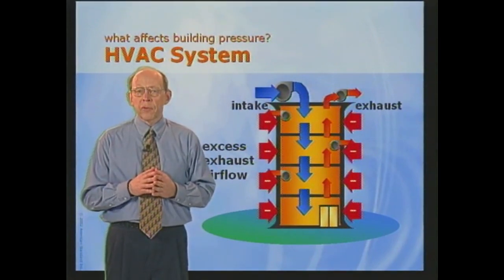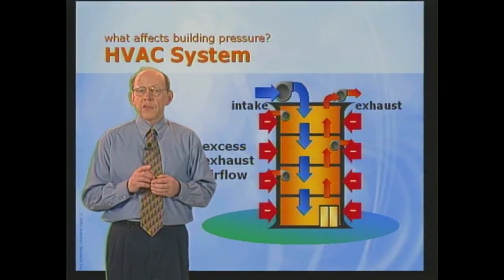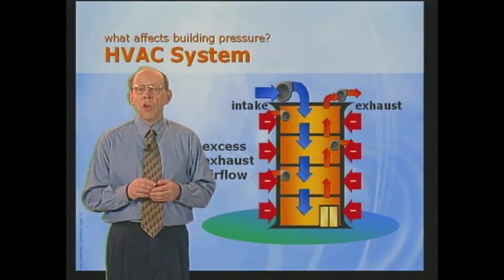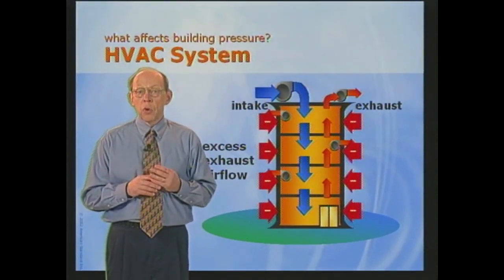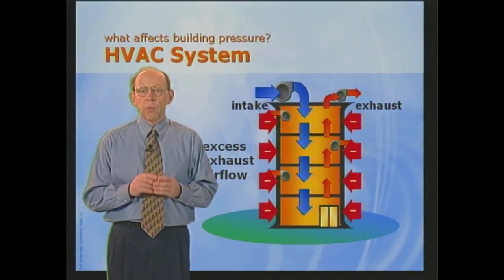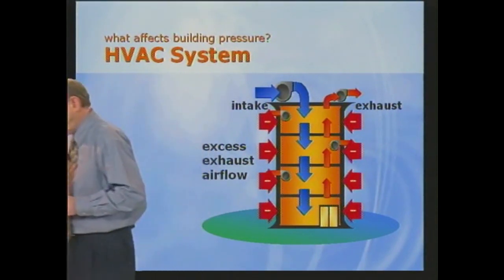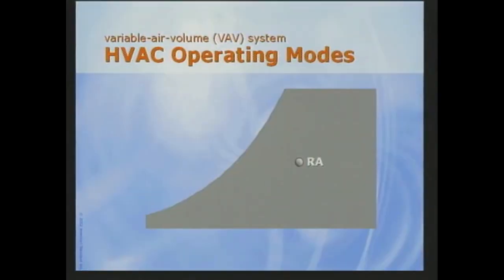Intake and exhaust airflow depend upon the HVAC system operating mode. Four operating modes are important when considering building pressure control. When it's hot outdoors, the system is in the cooling mode. Intake airflow is maintained at the minimum quantity required for proper ventilation.